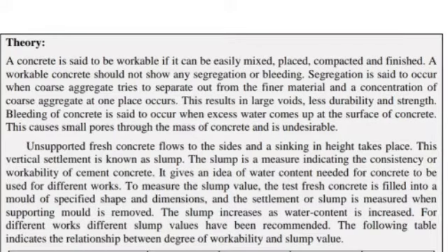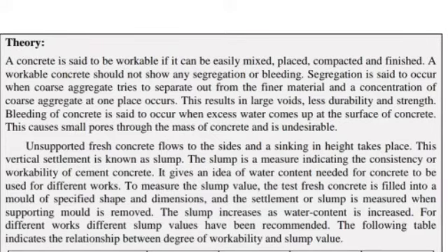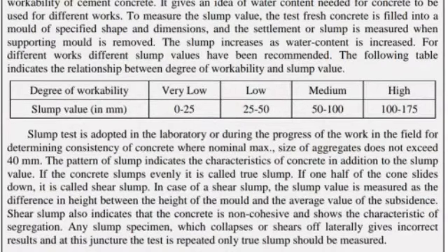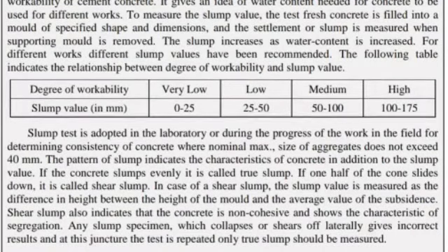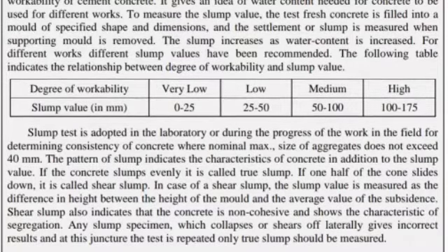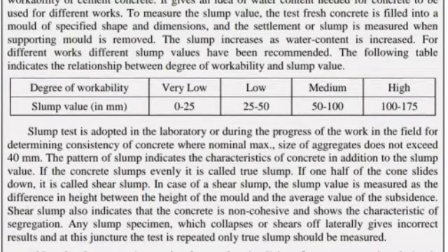The slump increases as water content is increased. For different works, different slump values have been recommended. The following table indicates the relationship between degree of workability and slump value. Slump test is adopted in laboratory or during the progress of the work in the field for determining consistency of concrete where nominal mix size of aggregates does not exceed 40 mm.